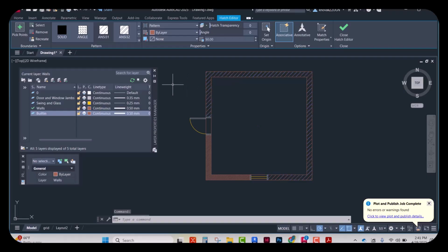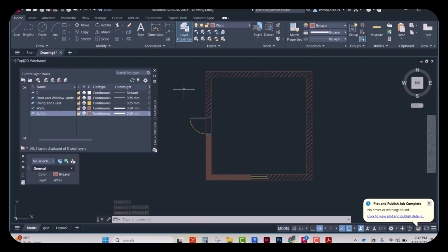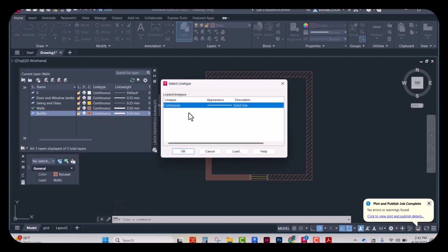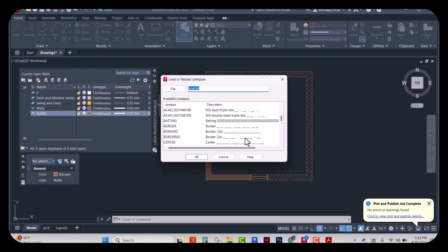I also want to go over different types of lines. We have a continuous solid line, and right now that's our only option here, but we can go to load, and then we have various dotted or dashed lines and different patterns as well, depending on your needs. Dashed lines often you want to use for upper cabinets. We want to show as built in, however, might be higher than that viewpoint line in a floor plan. Remember that a floor plan shows everything below 4 feet. And so if something is higher than that, i.e. the upper cabinets, we would show that as a dotted line to show that they still exist there. We just can't necessarily see them in a floor plan view.